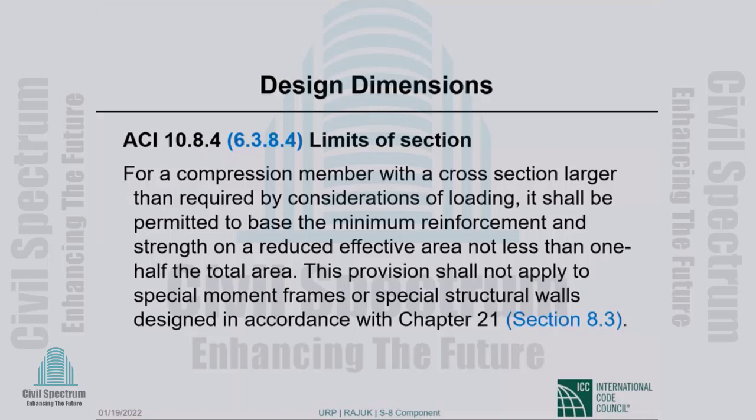Then you taper the reinforcement off. As you go up and the load decreases, you decrease the reinforcement. By the time you have hit 1%, you switch to a lower concrete strength and a higher reinforcement percentage. And then you do the same thing. You taper the reinforcement off.